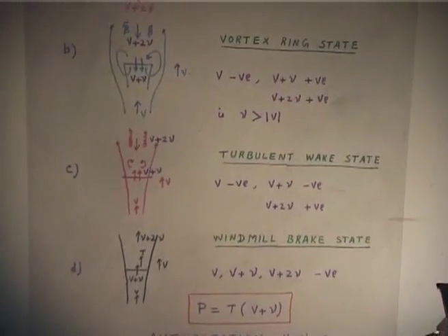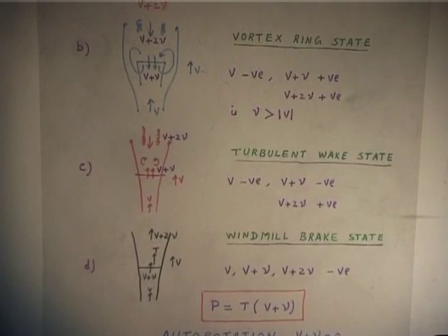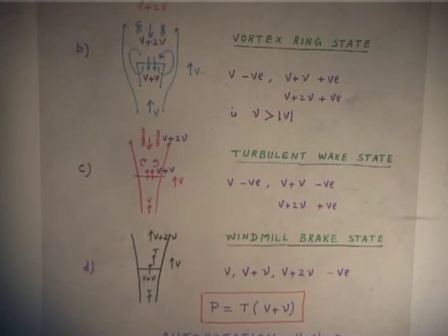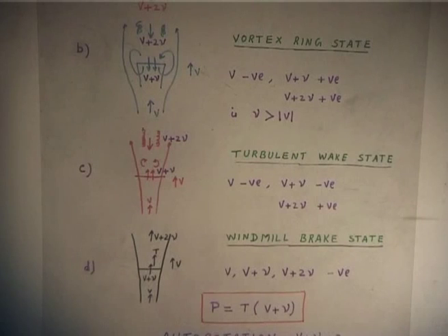They are not valid. Actually, there is no theory. So, momentum theory is not valid, but we need to have some theory, otherwise how will you calculate? So, that we will derive, then there is an approximation made mostly in test, and then they will draw the diagram and take it as some straight line, something like that, and then say okay, use this for auto rotation, that is all. If somebody asks what is the inflow, you just say okay, take this value, that is all. You can't calculate the inflow in auto rotation. You have to have an approximate theory. Even some publications are there, experimental tests, trying to fit a curve through that.